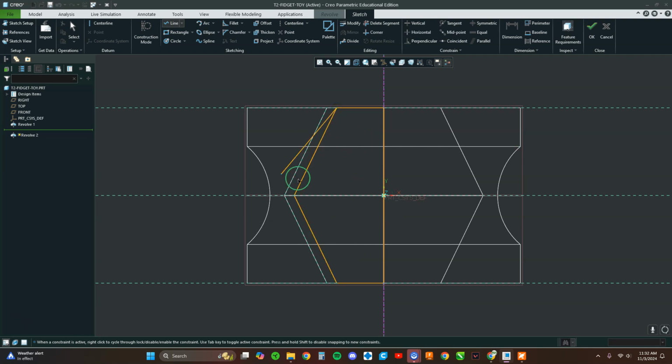All right, now you can either go up and hit the arrow, or you can middle click again, and we'll be able to see the shape. Now let's say you didn't get this dimension that just popped up for me. All right, go up and pick dimension, pick this line, and go right up above it, right in the middle of the two if you followed it up, and then middle click. Let's make it 0.05. That's going to be our clearance to make sure these two pieces can move independently.